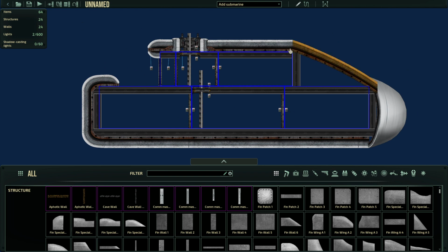If we change any of this information, where doors are placed, where ladders are placed, where hatches are placed, we now need to recalculate the nav points. That is a must. Anytime you make any change to the submarine's layout at all, for doors, ladders, hatches, rooms, hulls, regenerate your nav points, trim it for extraneous and errors, and then save.